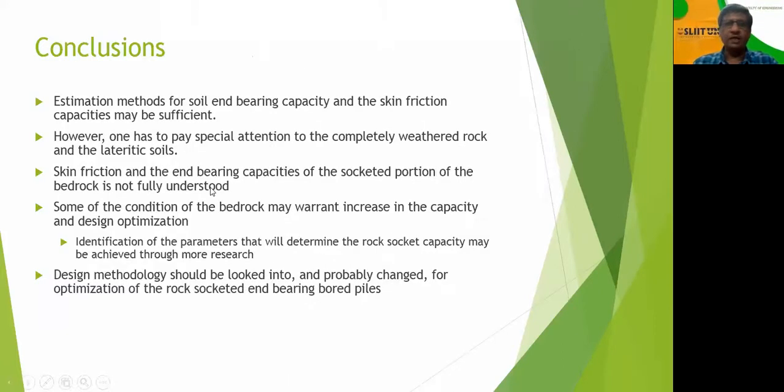is actually maybe partly supported by the findings here. And also the final conclusions regarding this estimation method for soil end bearing capacity and skin friction capacity may be sufficient. So that shows that what we use currently is sufficient, but we have to pay special attention to completely weathered rock and maybe lateritic soils that are found in Sri Lanka. So these are actually two exceptions. There may be more, and you have to have test results, but that is reasonably predicted.